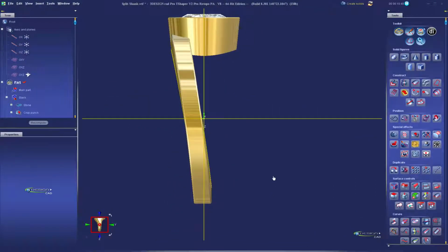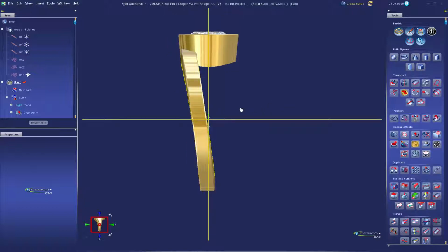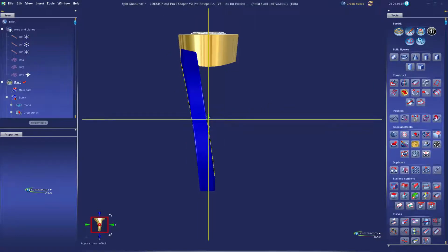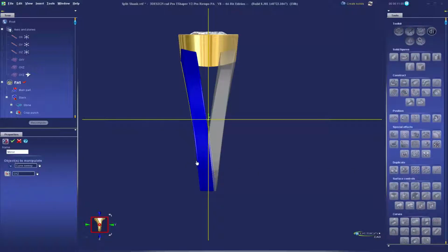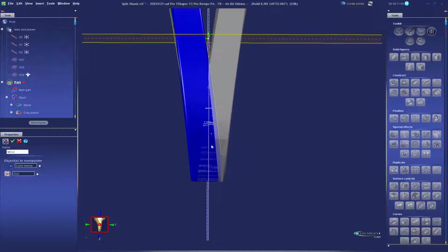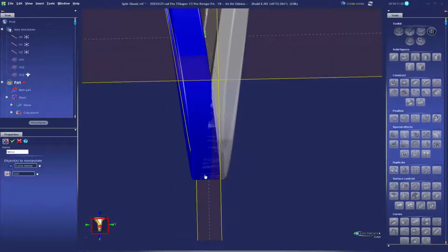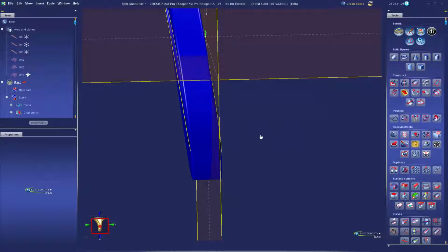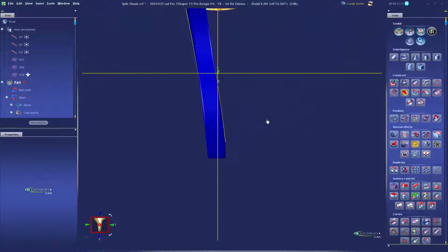Before we set up all of the micro cutting, that's going to make the piece really complex. So when we mirror it and try to Boolean, it's going to take a little more time to calculate. It'll work that way, but to simplify that, I'm going to take care of my other half of the ring now. To do that, I simply mirror this side to the other. Now, we're going to have a problem if we just do that, because we have these coplanar surfaces here. That's going to make a really messy Boolean. So to eliminate that, we just cut that extra bit off before we mirror it.